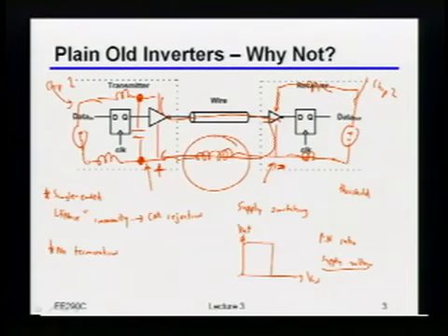So we'll actually talk about this some more. It turns out one of the biggest issues with single-ended drivers is that anytime you send current out through the chip, your return path always also has to go through that outside thing. And if those chips are far apart, guess what? No way in heck of guaranteeing that there's even remotely the same idea of what ground actually is. Now, don't get me wrong, it's not that this is completely busted. You can eventually make things work, but if you try to make this go at really high frequencies, pretty tricky. Pretty tough to really make it work the right way.